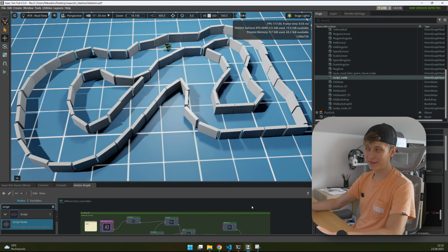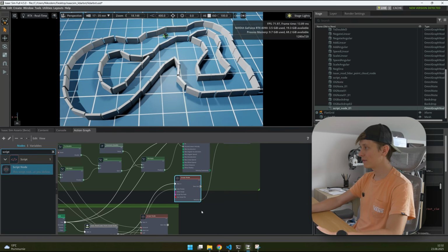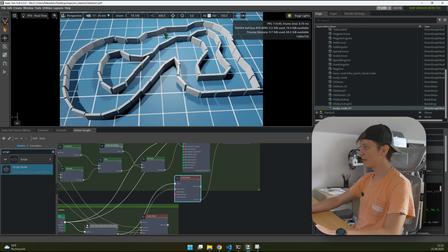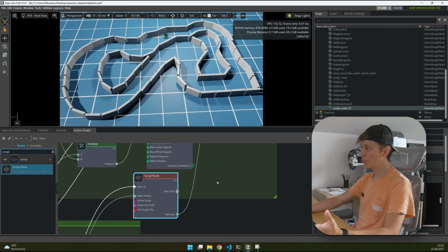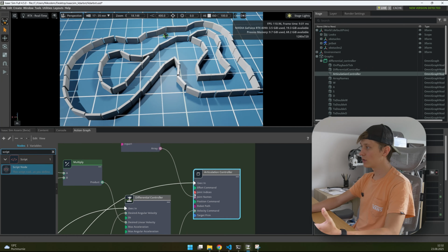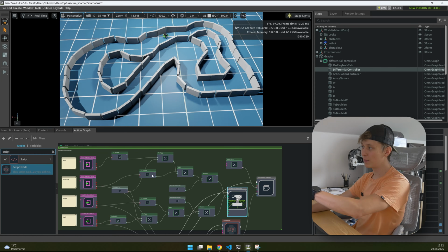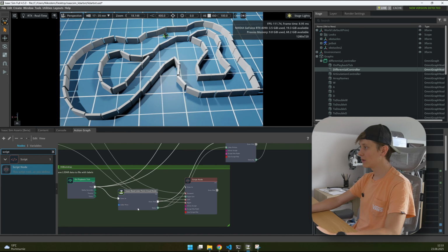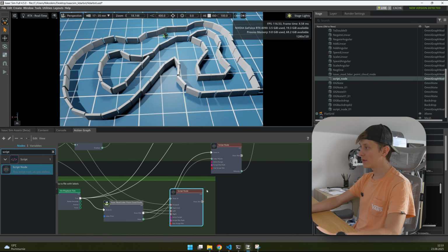Then I went back to Isaac Sim and created another custom Python script, the node for the action graph that you can see right here. Here I'm just loading the classifier from the file and selecting the features that have been generated. I'm controlling the robot by directly plugging the velocity values into the articulation controller, and skipping the differential controller setup. It is there, but it is not used. It's just easier to keep it there and connect a few things additionally. And of course, the LiDAR data is passed to the custom node instead of saving it to the file.